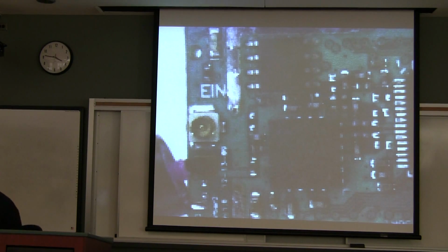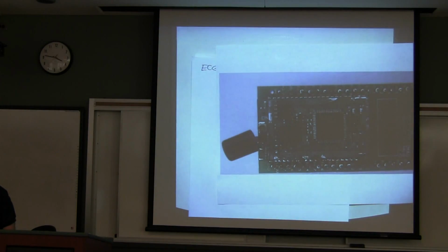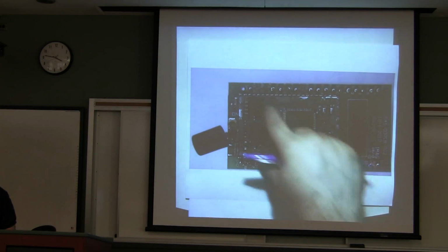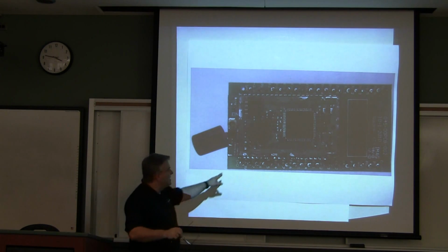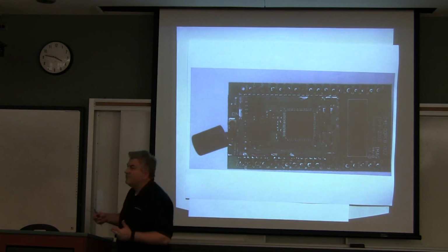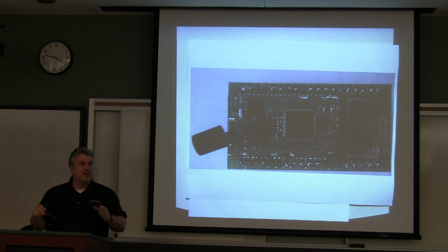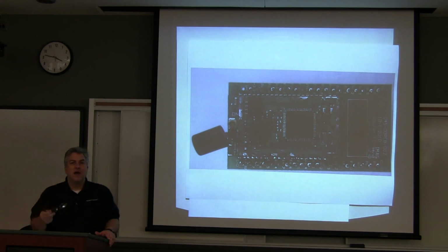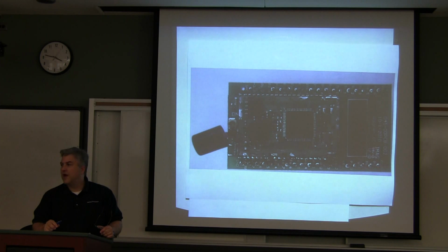And we actually took off a big giant metal can that sat over it. The thing you'll often find in devices that are RF based, cell phones, things like that, is that you put your radio frequency parts underneath a metal can because, let's see, most of you haven't been in EE, so maybe this will be obvious to you or not.